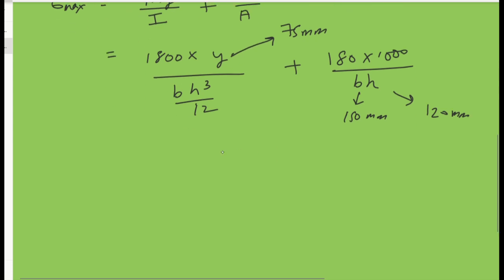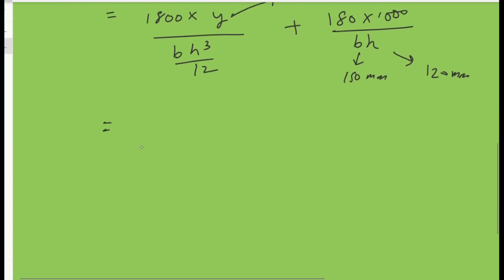We need to put the values in the SI unit and we will find out the stress. So directly, I is bh cube by 12, that is 150 h cube by 12.